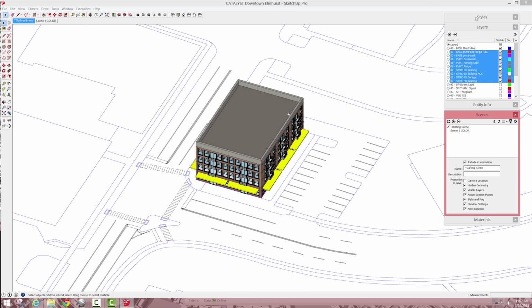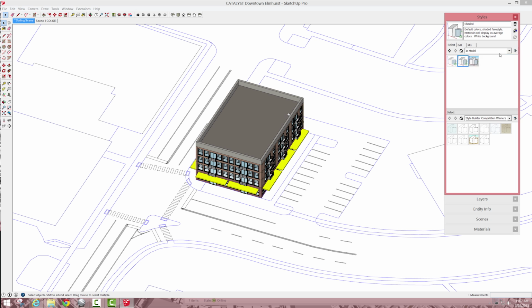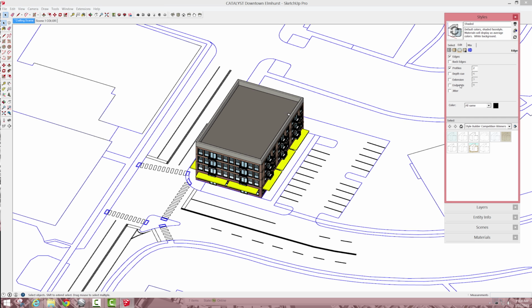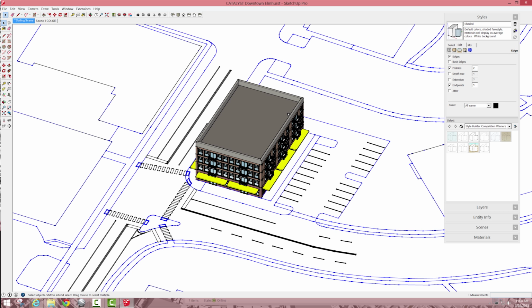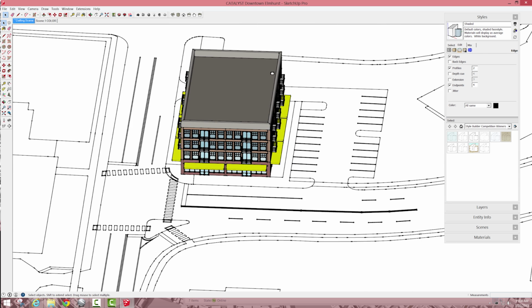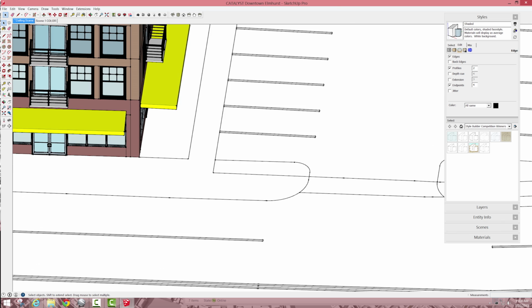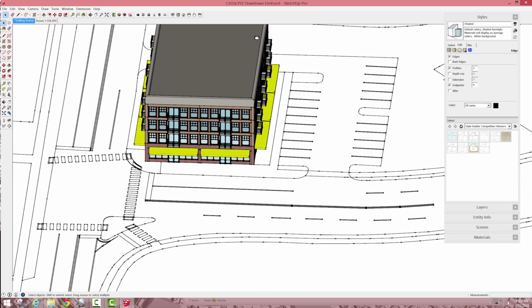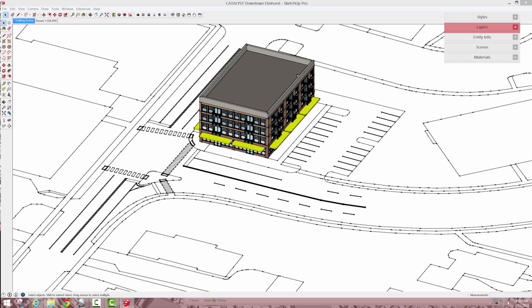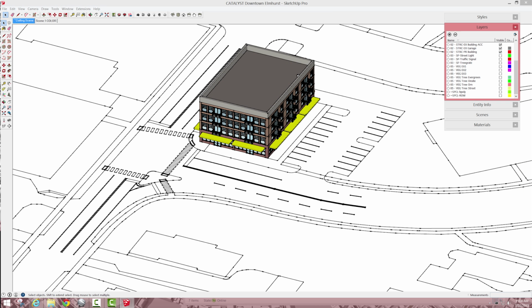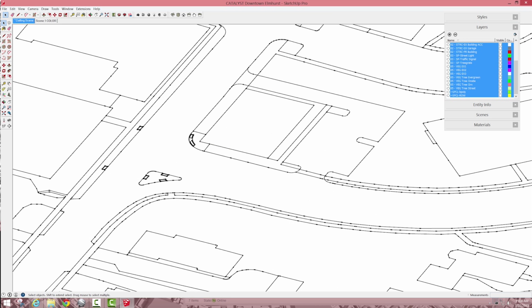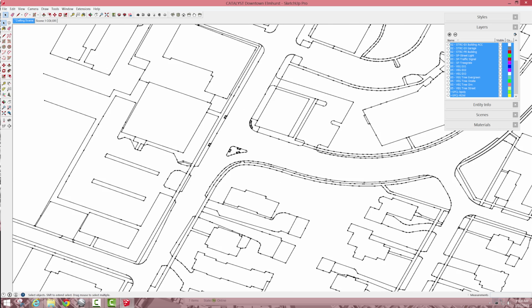Oh yeah, and then inside the draft scene, let's turn on profiles and endpoints, just so we can catch some errors if there are any, which I'm sure there are. Bringing stuff over from CAD into SketchUp sometimes doesn't close the gaps as well, so it's harder to make faces. So I'm going to turn off everything except for the illustrative base and start making the faces.